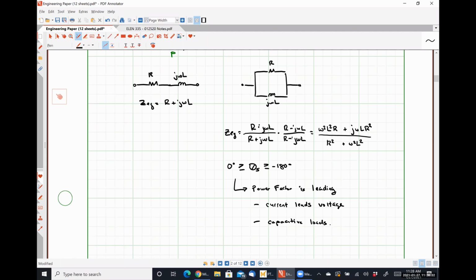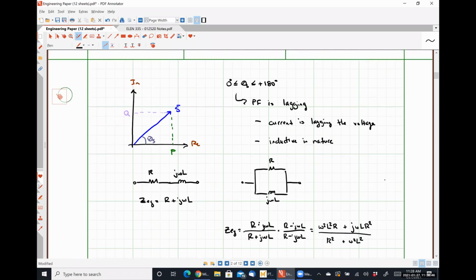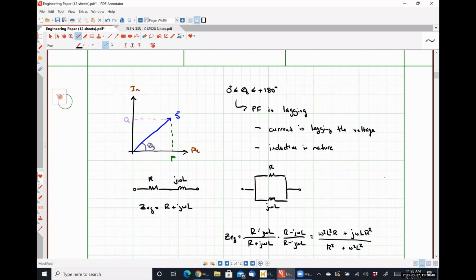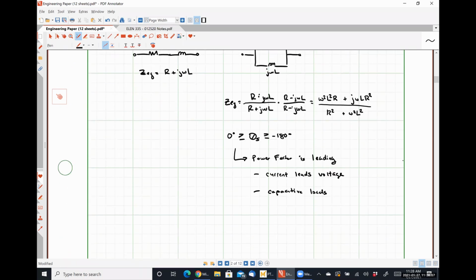And I shouldn't need to go through and tell you it's going to work for both series and parallel, because the math here tells us exactly why it's going to work out that way for our inductive example. So really the only other thing that I want to point out before we start getting into some numerical example problems would be that you can actually determine the power factor specifically, but no other quantity, without actually knowing voltages or currents across your load, right?